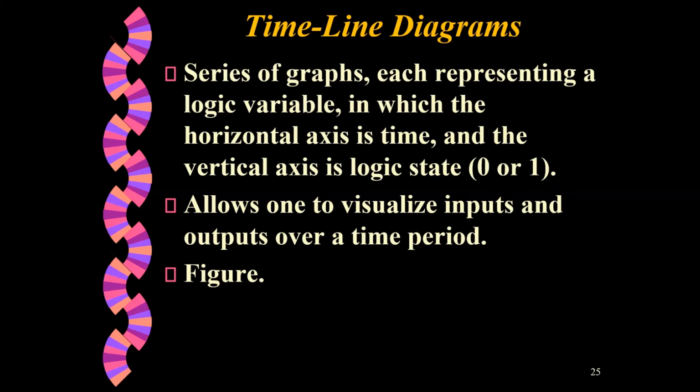These are the key steps. Number one, understand the problem completely as to what is required to be automated. Second, put logical statements on the basis of some inputs and outputs that are going to control the process. Plain English. Then put the truth table. Analyze. You, the designer, analyze the truth table and decide on when the output should be true or not true. Develop the equations.